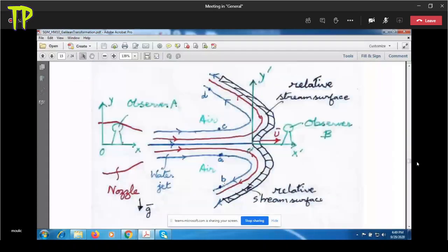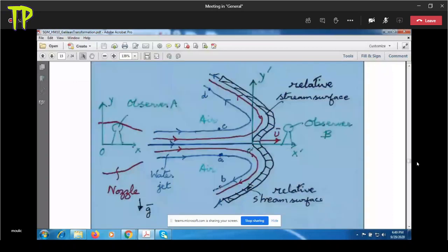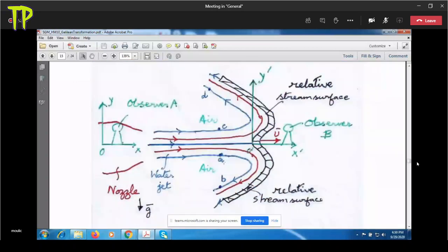And if the velocity at B is less than the velocity at A, that is good news for you as a mechanical engineer, because then you can see the kinetic energy of the liquid jet being converted to work. So there will be a resisting force on this vane so that the velocity is constant, otherwise it will accelerate. So if there is a resisting force and it moves, then you have work done. But simultaneously, the kinetic energy of the liquid jet must decrease.